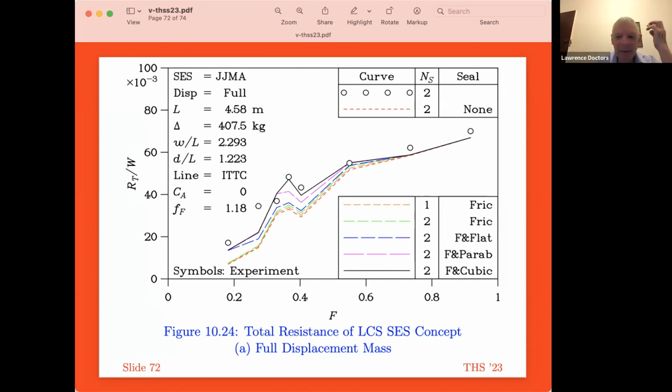Yes, yes. Now, people like BHC and other skirt designers played around with that slightly and took a few liberties with that straight line. They cut the tips off and did various other things. But basically, the fundamental principle of the finger is that it's self-stable just with a simple pressure behind it. And because of those various notable features, Dennis Bliss, through HDL, was awarded the patent for that device. HDL had that patent running for about 20 years.